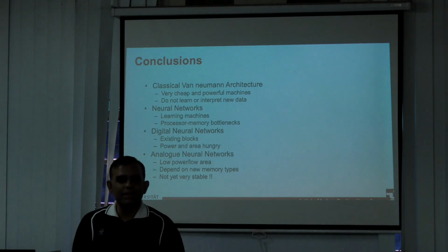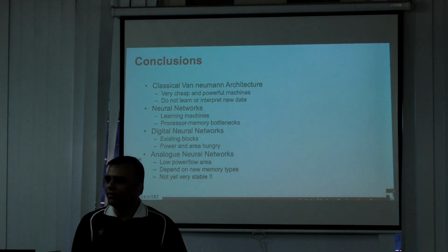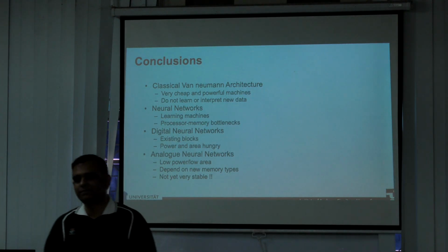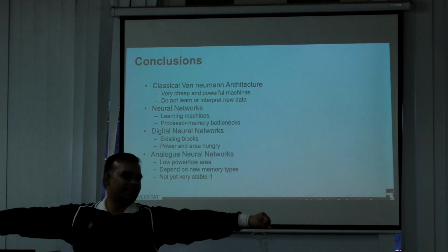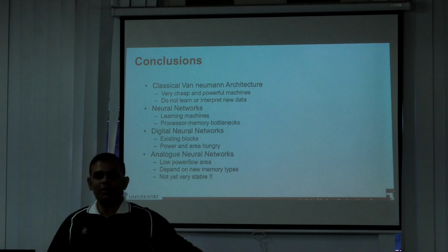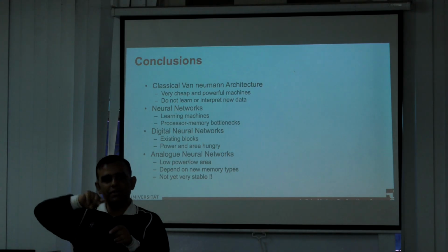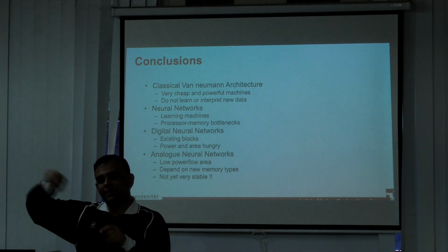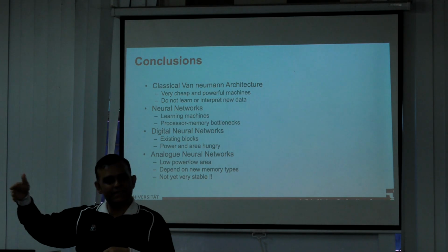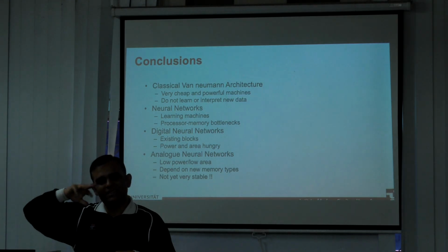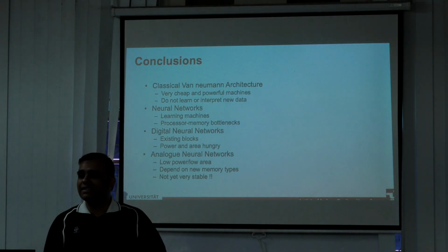Okay. How can we make resistances in the chip? One is a memristor. Say our process does not have a memristor. What other ways can we make a resistor? We can make a long wire, that's a resistor. It's a small resistance. Or we can use a transistor. Remember, transistor operation goes up and then flat lines. The time it is going up, it looks like a resistor. It is a resistor. It's a voltage dependent resistor based on the gate voltage, and I can change its resistance slightly by applying different gate voltages. Okay, so we can use a transistor as a resistor.